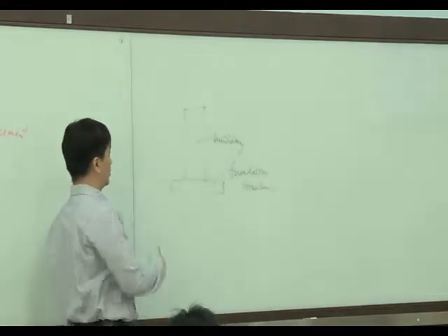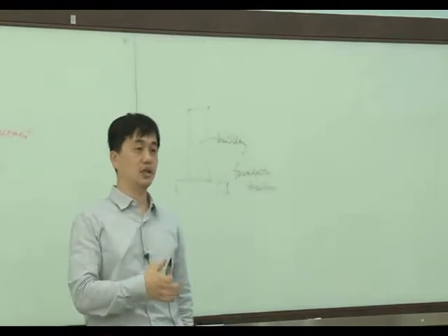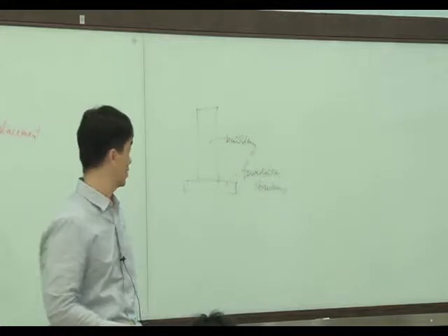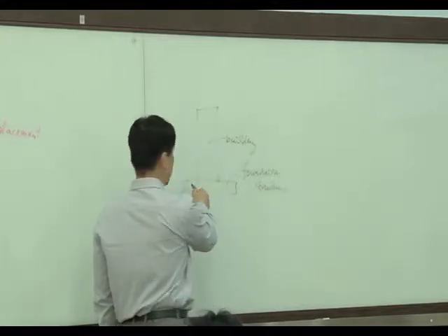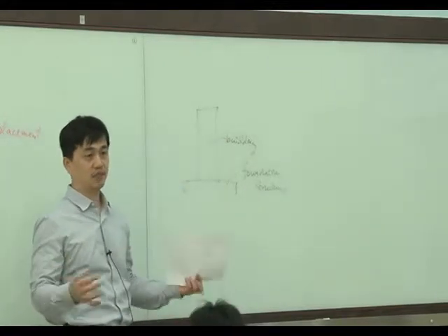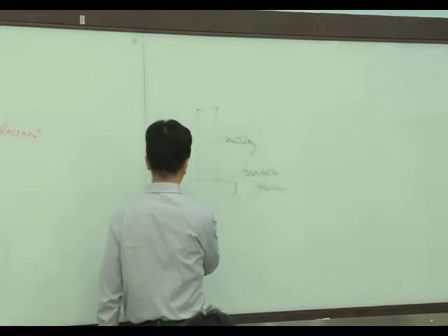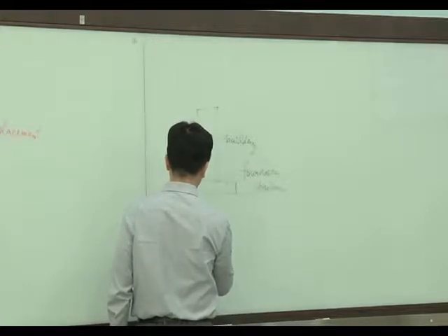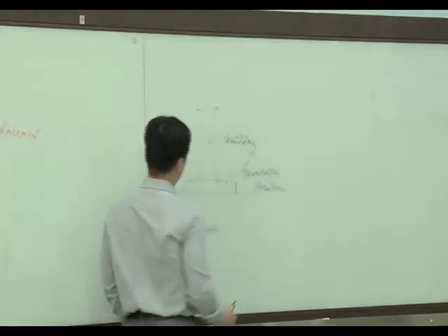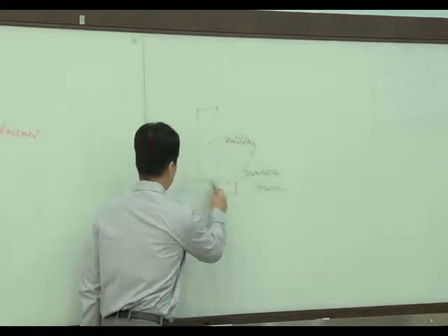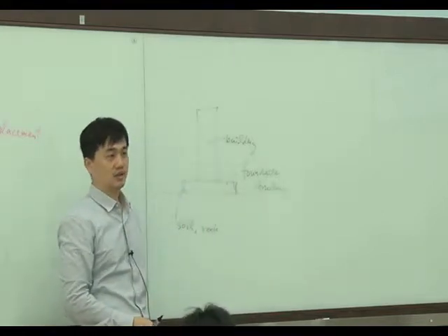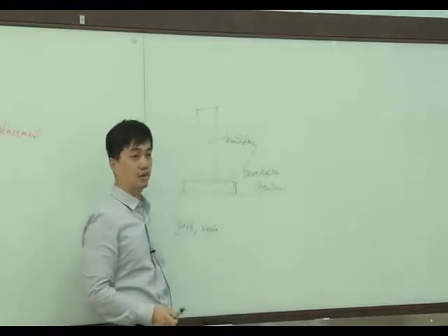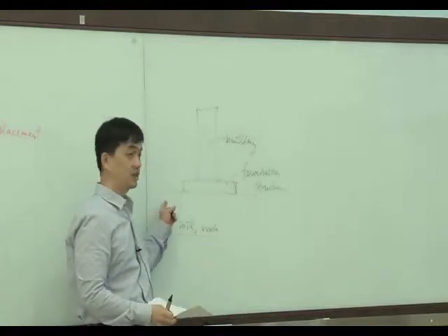We build the building or any structure on the foundation structure. You can think this is something like a big mat. And here we have soil or rock. So this foundation structure actually behaves like a beam. And this soil or rock, the surface of the earth, is an elastic foundation.